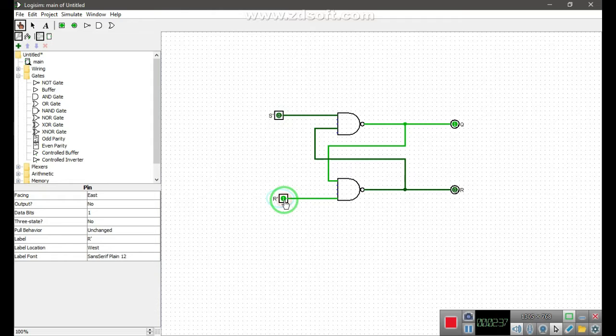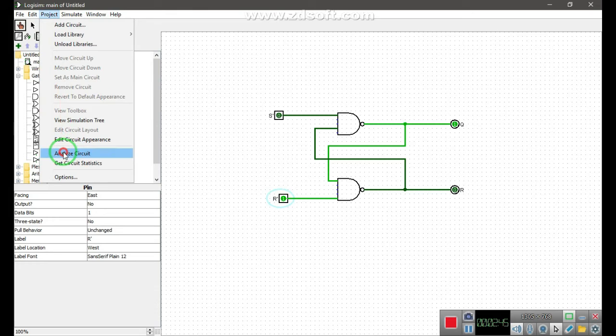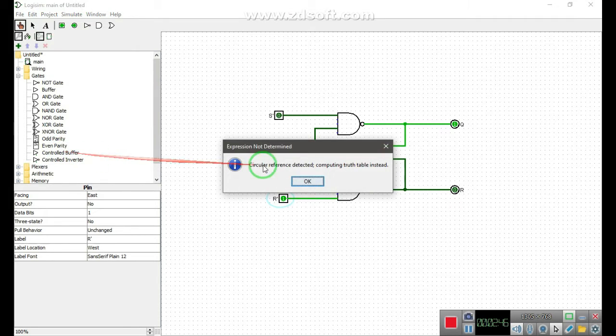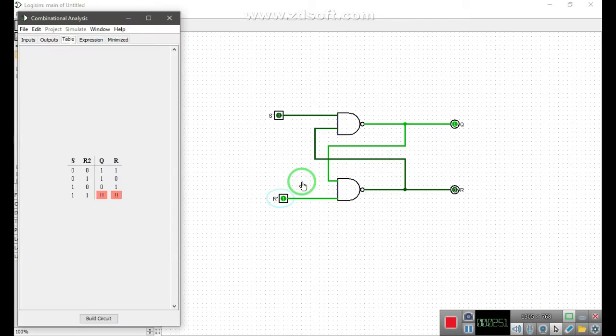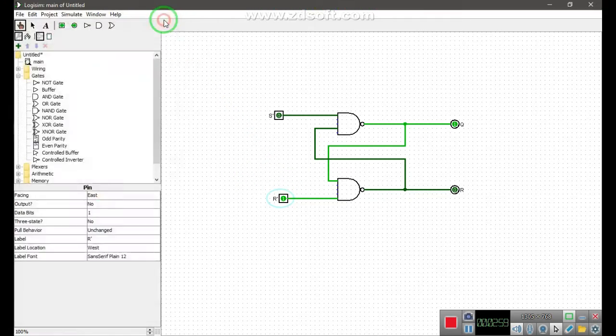If the set input S now changes state to logic 1 with input capital R remaining at logic 1, the output Q still remains low at logic level 0 and there is no change of state. Therefore the flip-flop circuit reset state has also been latched, and we can define the set-reset action in this.